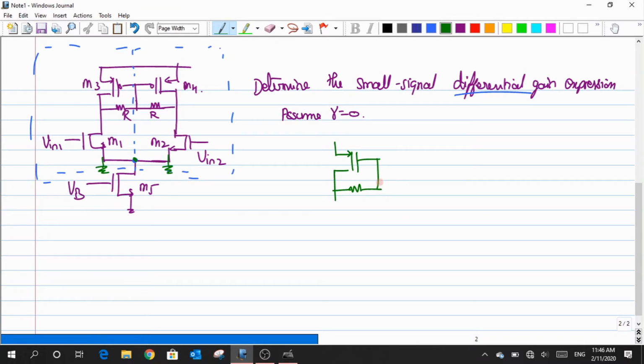Yeah, there is one more question for you guys. What happens to this node? Yeah, so we said that this particular node is common, so we just plug that node to the ground. But what about these nodes? Okay, so even this node is actually connecting both the circuits. This part of the circuit is making a connection with the other part of my circuit. Basically, this node acts as a kind of common bridge between both the circuits. So this also will be driven to ground.